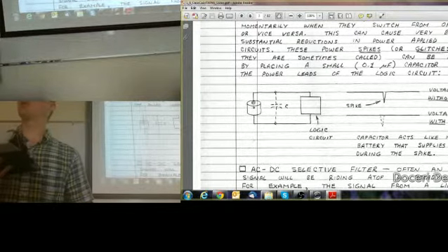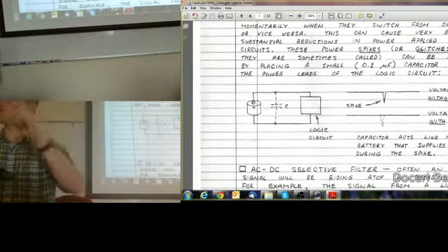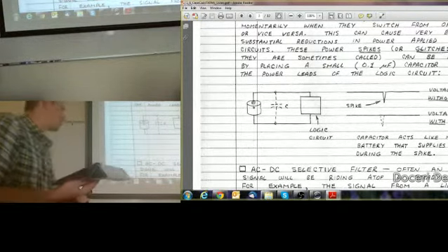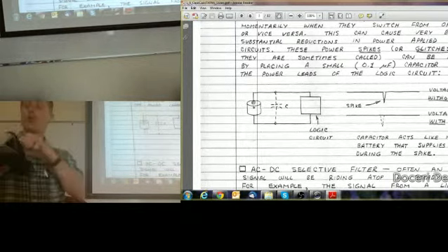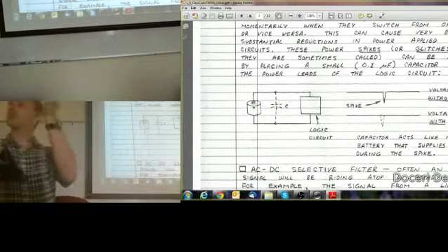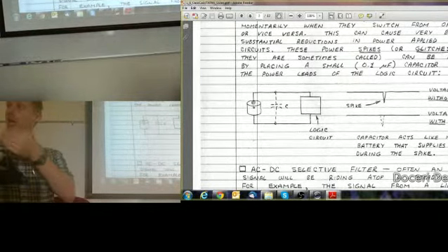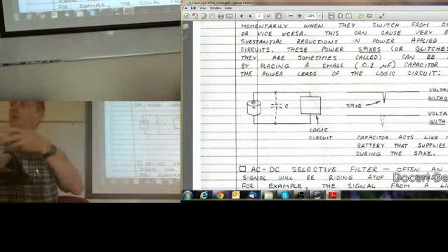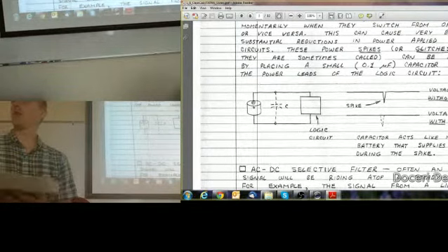Look at your TTL logic levels. There's a little bit of room you've got there. If you're on the bottom, you only have 200 millivolts or something, maybe 300. So it can cause problems. And then when you add the inductance of the wire that's actually delivering the current, now you've got electromagnetic induction. When you have a current change, you have a magnetic field, and then you have an induced voltage. So added together, you've got a problem.